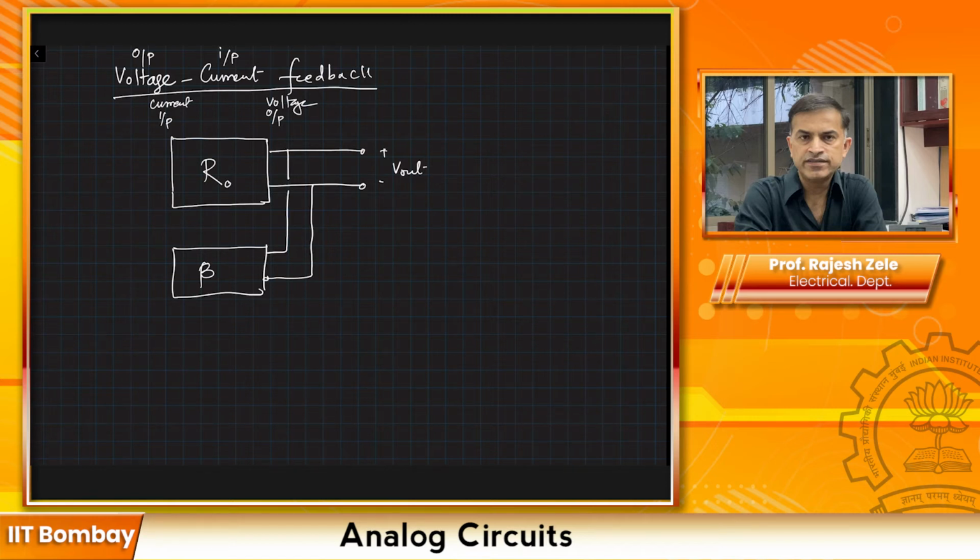Okay, so input current, which means that I have a signal current source I in, which is being applied over here. Since my feedback coming in is also current, then we can connect it like this. So part of the current is being stolen by the feedback factor here, and then the final error current is going in.